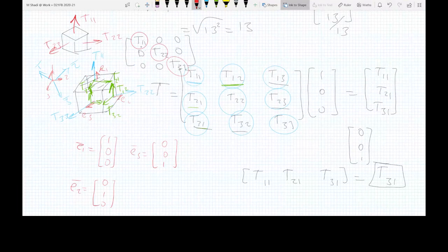You see that? So this is the thing. The maximum normal stresses would happen on this specific coordinate system, which I don't know. I mean, there will be a coordinate system, but I don't know it. In this coordinate system, if I project the stress tensor, I would only have these numbers in there. And these numbers are certainly going to be the maximum normal stresses. So this T11 in this coordinate system here is going to be certainly larger than T11 in this coordinate system, and certainly larger than T11 in this coordinate system.